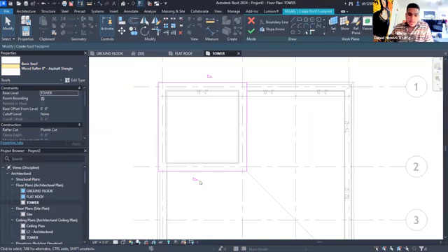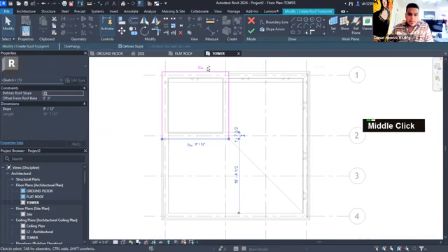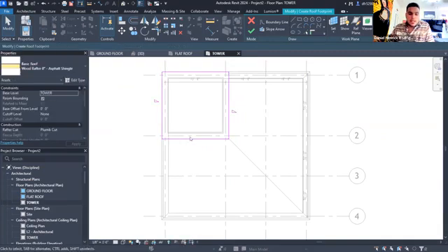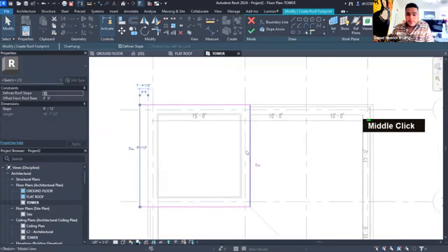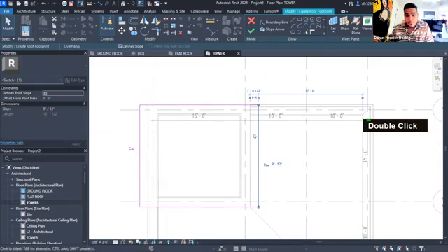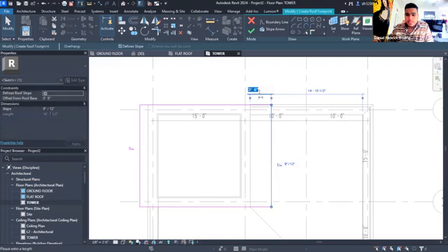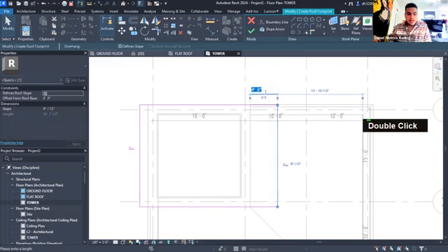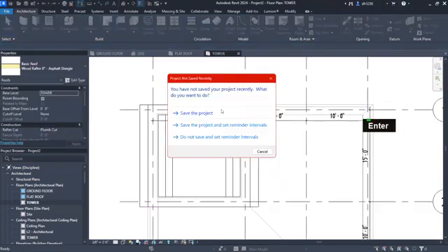So back to Revit, the sides that don't have, actually these are backwards. These don't have a slope, and then these have a slope. Okay, so the sides that have a slope are a foot, 4.5 inches away. Oh, I accidentally pulled the line away on both sides. Whenever you pull the line, you can just click on that measurement because you already selected the line. There you go. Now, once we create this roof,